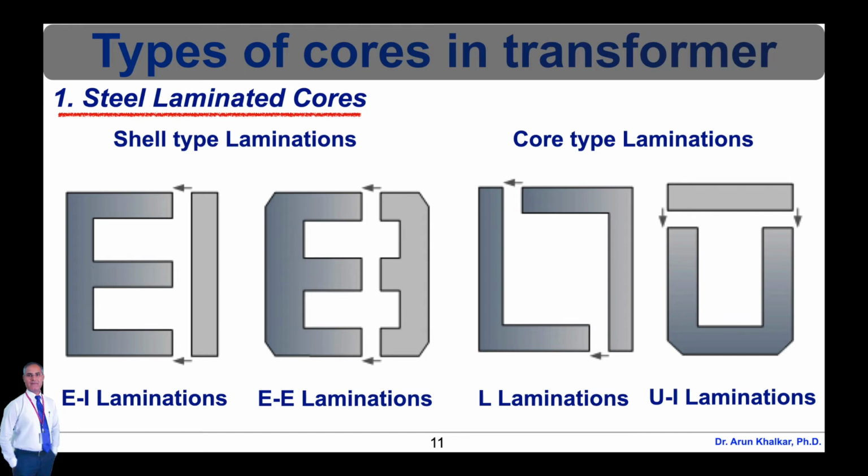These individual laminations are tightly attached together during the transformer's construction to reduce the reluctance of the air gap at the joints, producing a highly saturated magnetic flux density. Transformer core laminations are usually stacked alternately to each other to produce an overlapping joint, with more lamination pairs being added to make up the correct core thickness. This alternate stacking also gives the transformer the advantage of reduced flux leakage and iron losses.